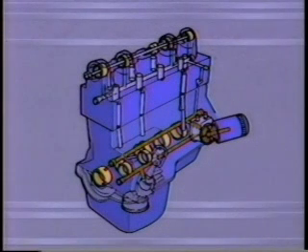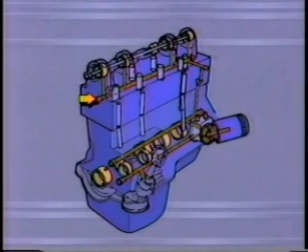And really, you brought it up yourself by mentioning the different upper engine designs, like the overhead cam, dual overhead cam, and rocker arm shaft. These components, like any other, must be lubricated, and it's typically through an oil passage. Let me show you some examples. In this 4-cylinder overhead cam design, you can see there is an oil passage right off the main oil gallery. This passage feeds another gallery in the cylinder head, which in turn pressure feeds the camshaft bearings and lifters.